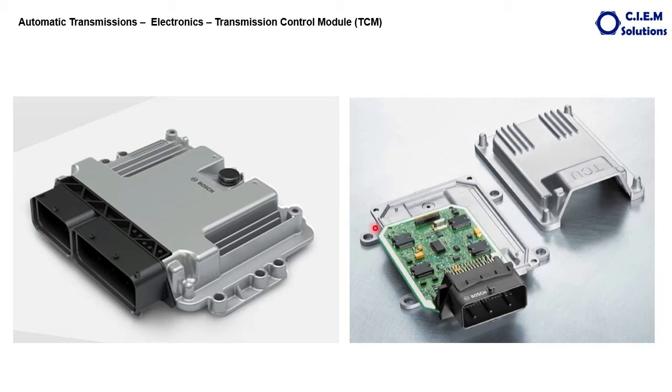The job of this transmission control module, which somebody also calls the transmission control unit, TCU, is to take the inputs from the various parts of the vehicle and process those inputs in this processor. This is a kind of computer. It processes these inputs and gives signals through the output wiring to the various solenoids to execute and engage the desired gear depending upon the dynamic road conditions.